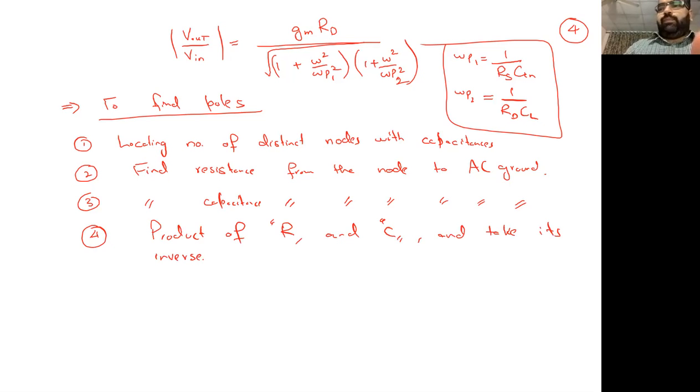Okay. So we can apply this to another example to see the common gate configuration, how it's going to work, and then we can see variants of those things. At this moment, we are talking about only those capacitances which are just coming from a node to the AC ground, but there can be some capacitance in the middle. How are we going to deal with those situations, because they also come. So let's just talk about the common gate scenario, and then we can move on towards a different scenario, and we can apply a powerful concept of a Miller capacitance.